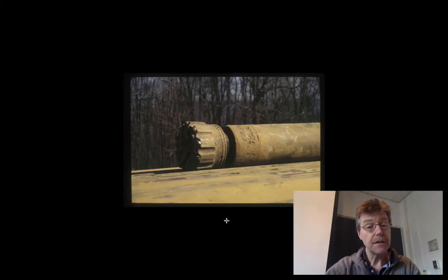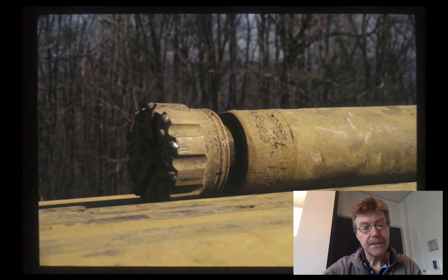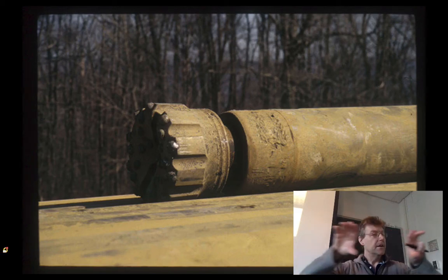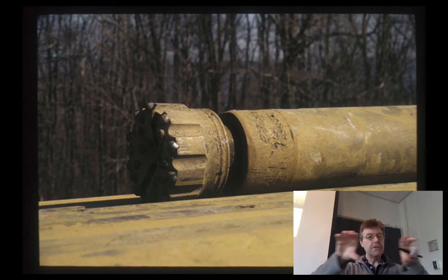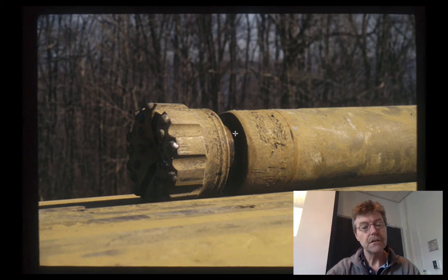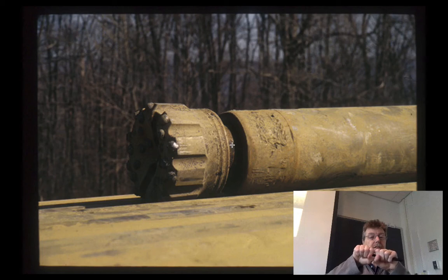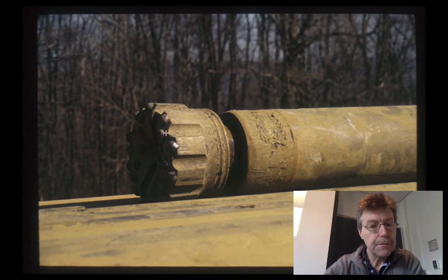And so this is the same rotary drill, but instead of tricones, you can see that it's kind of disconnected here. So you can imagine maybe that this left-hand bit is moving in and out, up and down on a central spindle inside this. So all that happens is you power high-pressure air or water or drilling mud down here, and as it comes out of here, it drives this like a jackhammer. So there's a little valve that makes this end drive like a jackhammer. It has these little button bits on the end which bang against the end of the borehole.